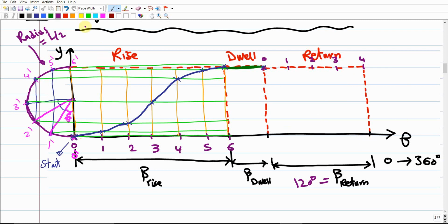And here we have to draw a semicircle. This semicircle, its center point should be at the middle of this vertical line. You're going to fix the compass with the middle tip here and touch with the lead tip on this point. Then you're going to draw the semicircle. Try to be as accurate as you can in terms of the drawing. Okay, so we got the semicircle.